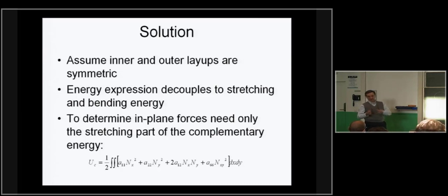It's not as easy as I made it sound, but yes, you can make it, and in many cases it will work. But it's not a blind thing, let's just add material here, because you will soon find that your buckling load goes down after a while if you keep adding material. So it's not an easy problem to find the optimum.